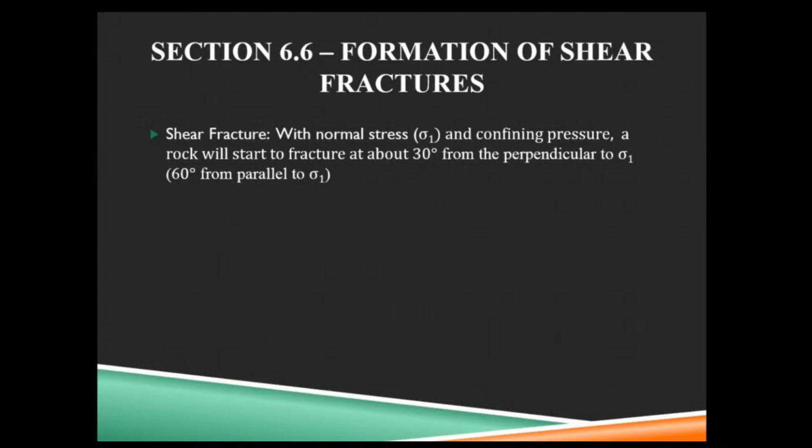So, that upper surface that we're pushing down on, if we drop down 30 degrees from that surface, or come 60 degrees from parallel to sigma 1, so we're pushing straight down, come up 60 degrees from that straight down, it's the same angle. That's approximately the angle the crack's going to form.